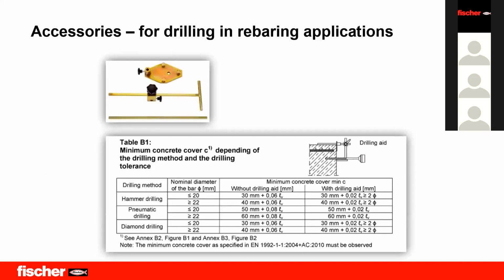Let's say for a drilling rebar application, we do require a drilling aid. It's just to avoid damaging the cover of the concrete or reinforced structures, and also to make sure that you don't damage any reinforcement rebar inside the structure. So we have to use a drilling aid.